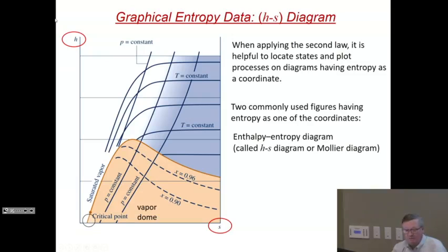Remember that when we talked about liquids and incompressible liquids, the enthalpy didn't vary very much with temperature, with pressure, for example. So very often you use as enthalpy the value that the enthalpy had in the saturated liquid region. Well, so this is actually the same thing. This difference is quite small here. Now, like before, if we have an isobar, it looks like this. And as you go from here to here, well, you can't get to zero here. This is a decrease in the quality of your vapor.